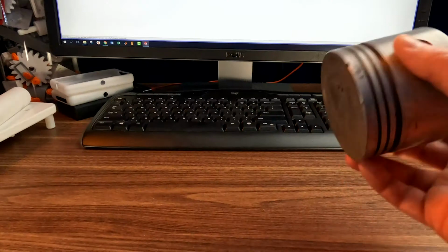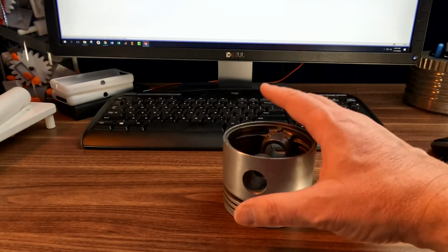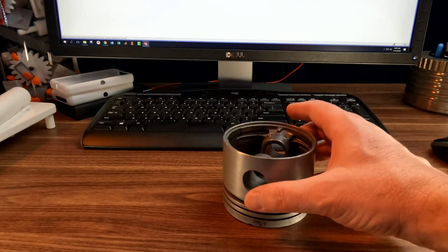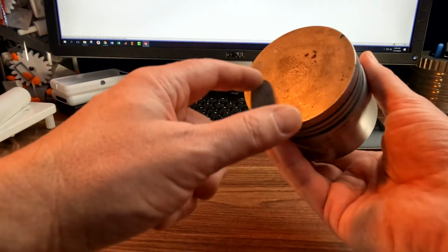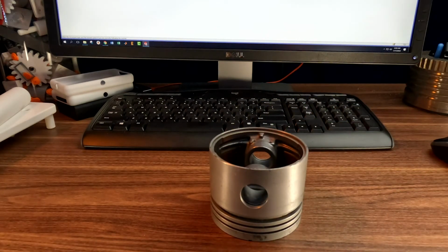And whenever we're working on CAD assemblies, we're working to reduce the degrees of freedom so that the parts become constrained to each other. So for example, if I wanted to, in a CAD model, reduce some degrees of freedom for this piston, I would say to myself, well, I'm going to set the piston on the table. And as I set the piston on the table, one of the things I would do here would be that I would mate this surface to this surface. And that would be an assembly mate.